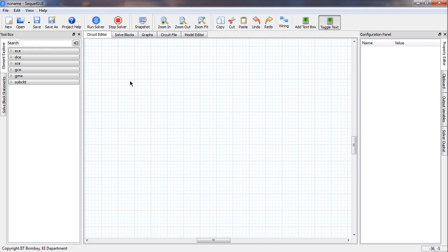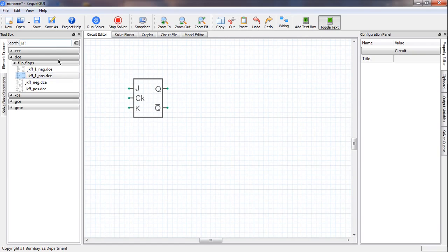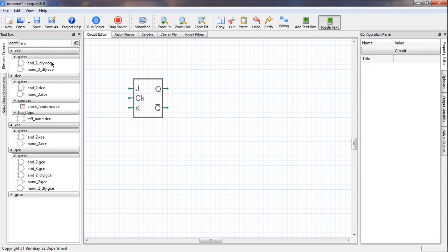Let us now start constructing the schematic for the counter. First, let us get the components, and we will begin with the JK flip-flop. There is an element called JKFF1, for positive edge triggered flip-flop. That is the one. We then need to get AND gates. We can just get one right now and then copy it later. OR.